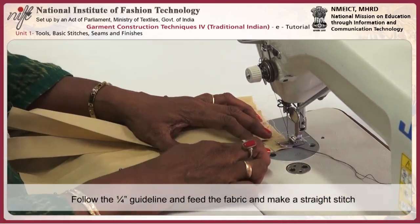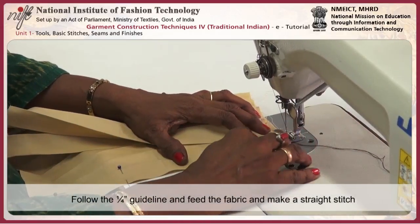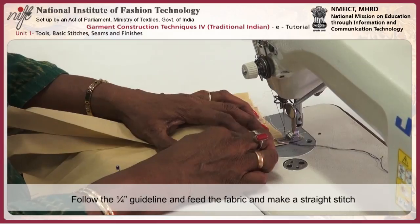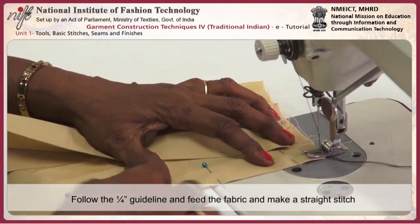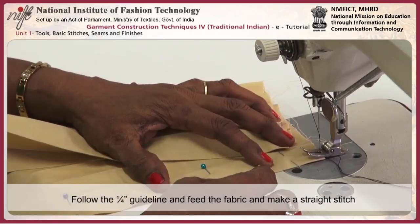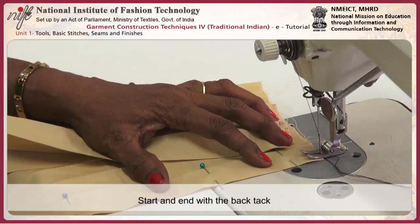Follow the guideline. There is a guideline in the machine. You have to feed the fabric by following this quadrant guideline and then do a straight stitch. Doing a straight stitch is very important, and we have to start with the back tack and end with the back tack. It's a normal procedure.